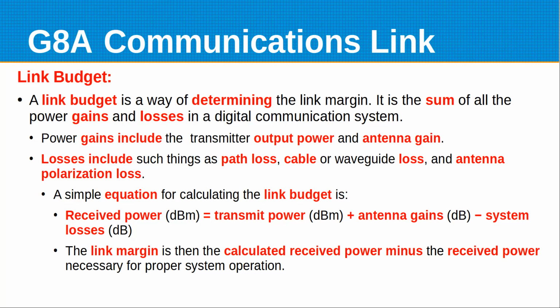And you get to count it again on receiving. So I'm now up to 92 dB gain on top of my 61 dBm from the transmitter. So I've got what? I'm not good at math in my head. We're a little over 100 and something, maybe. I might have some losses with coax and other things, so you knock off a few dB.